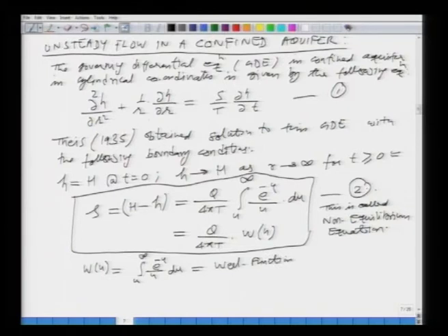It is encountered in this kind of situation for aquifers or wells, that is why it is called the well function in groundwater hydrology. And u is an intermediate parameter which involves time. U is something which represents time and also the radial distance r. So, u is r squared S over 4 capital T and small t.